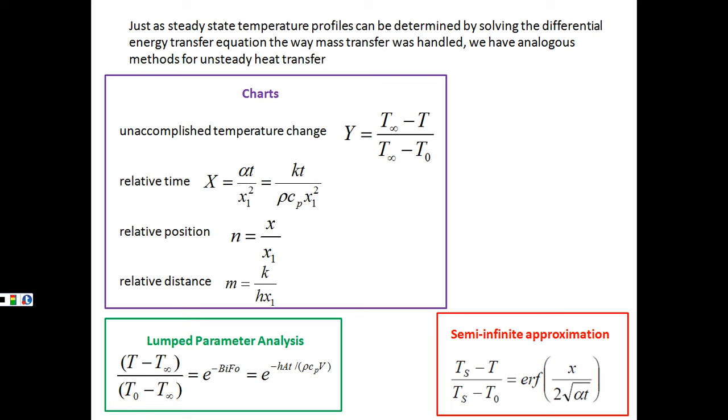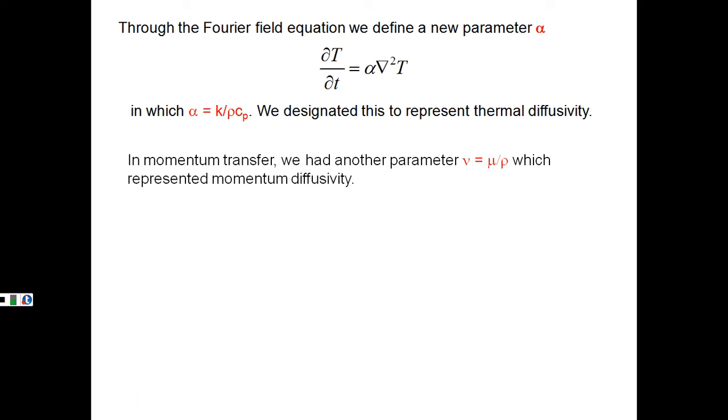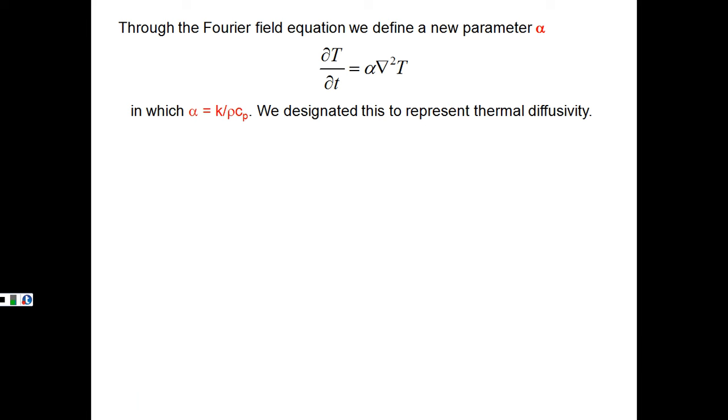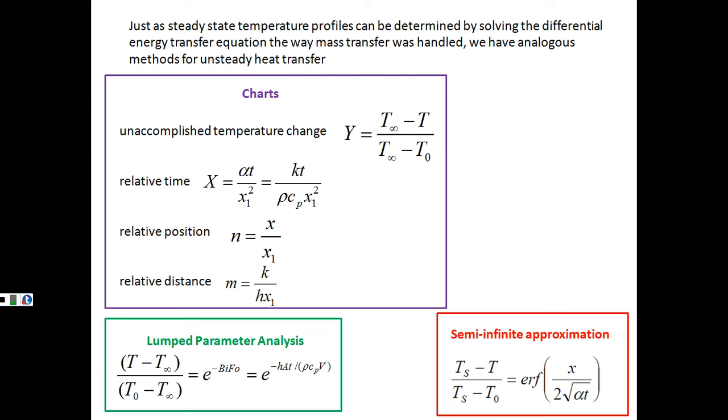So I came across last week a textbook example that I thought was so nice, and it made me pine for a really great biotransport textbook that would use these types of analogies to distill down some of what we teach you. But this particular textbook on heat transfer gave this really nice analogy on the significance of the Biot number. So they said, okay, pretend that the volume of interest that you're looking at, whether it's a stainless steel ball bearing or some gel slab, is like an island. And you have boats that can come up to your island and let out passengers. And then you have a bus system, which is moving people around the island to disperse them.